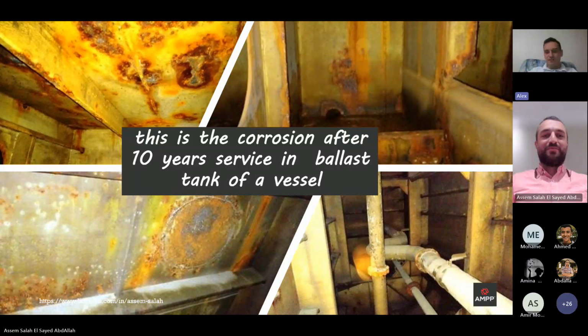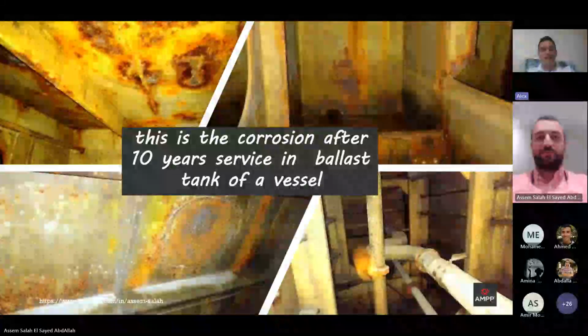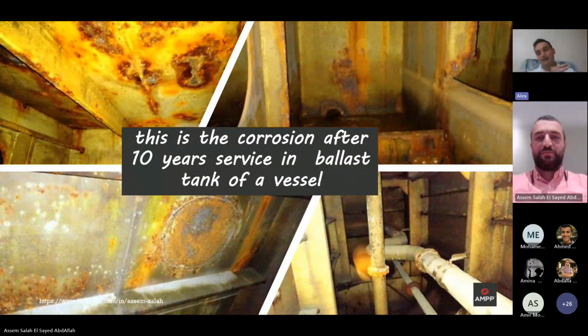Yes, I have chosen a couple of photos just to illustrate. Now you can see rusty spots in a ballast tank. The ballast tanks of a vessel are a very important area of a ship, and the ship operators or ship owners must keep this area in good condition all the time. And we can see that the ballast tanks were coated 10 years ago, maybe during the construction of the vessel, most likely with 2 layers of paint, 300 or 200 microns, minimum 250 microns.